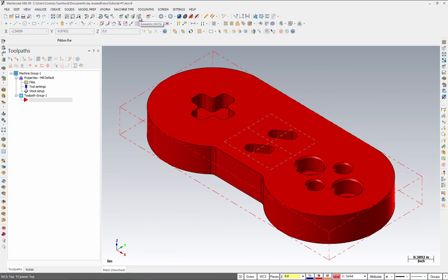In the next operation, we have to create a 2D high-speed dynamic mill. A 2D high-speed dynamic mill utilizes the entire flute length of the cutting tools to produce the smoothest, most efficient tool motion for high-speed pocketing. The toolpath supports a custom entry method and many others.